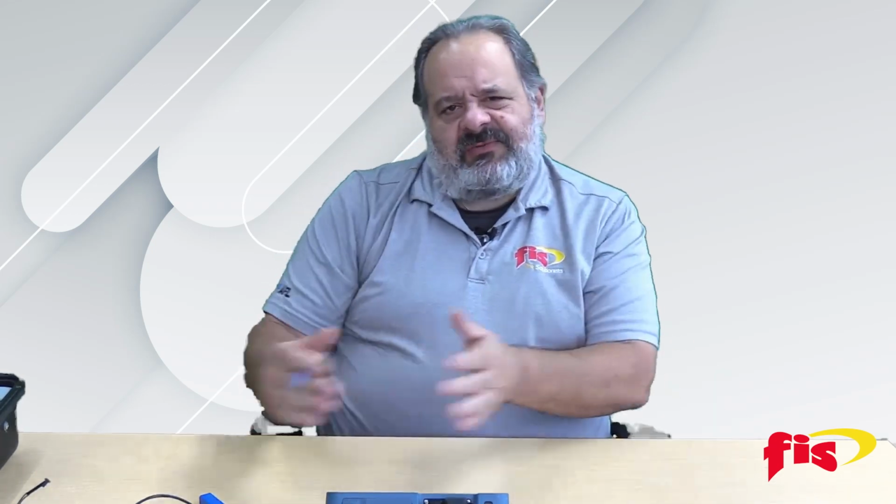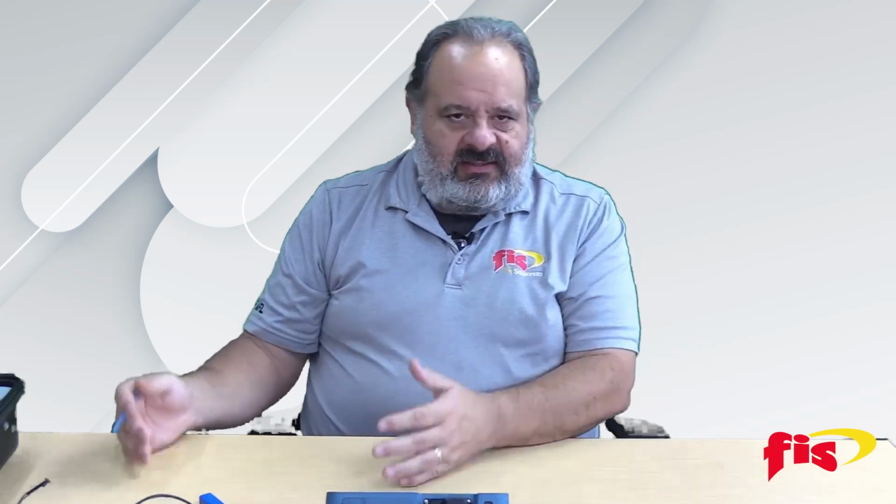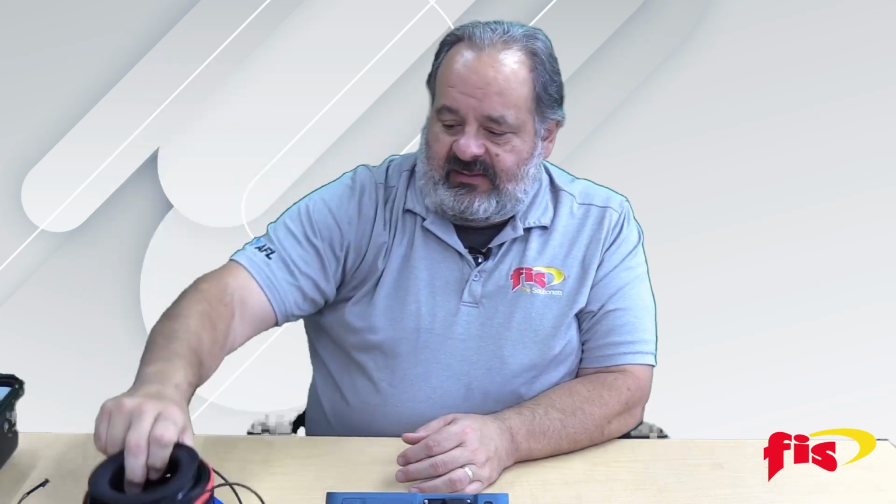So launch cables, and okay, we can say launch and receive cables. These are cables that we are putting in front and at the end of any cable that we're testing with an OTDR. You can see this is a common one. We call them little hockey puck ones. So why do we use them?